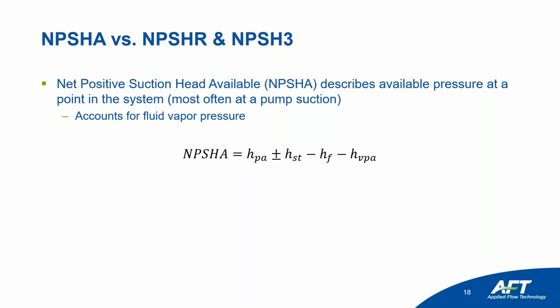Here is the equation. And you might not be an equation kind of guy, but it is helpful to understand the individual terms. So it essentially represents, like, do I have enough pressure at the suction side of my pump so I don't cavitate, obviously relative to what's required. But this is the equation. You have a starting head, like one of your boundary conditions. You have elevation change to get to your pump, and then you have friction to get to your pump. All of that is going to, it could be dropping the pressure, especially the friction if it's high. That all has to be a margin above the vapor pressure, right? Because if it's below the vapor pressure, you're cavitating without any sort of flow.